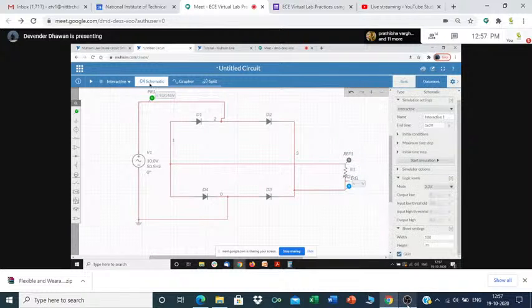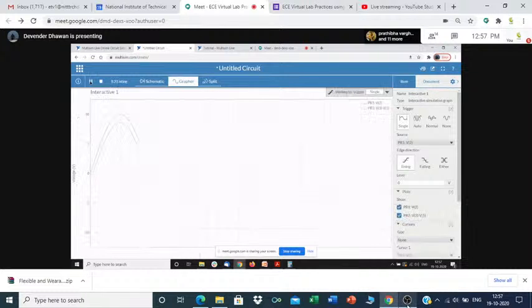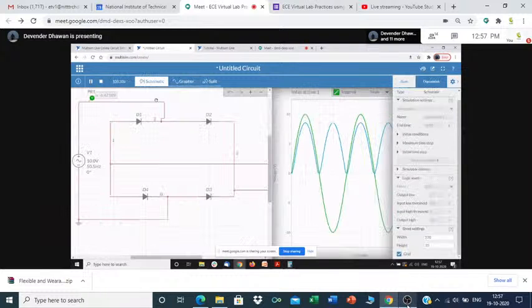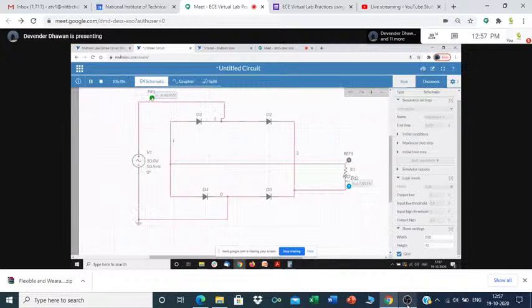Okay, so reference means just like putting voltmeters across, exactly, ma'am. Generally, if I see this probe, you see one terminal only. By default, the measurement will happen at this point, which will be the positive end. The negative end of this voltmeter will go to the ground. So by default, that is the connection.